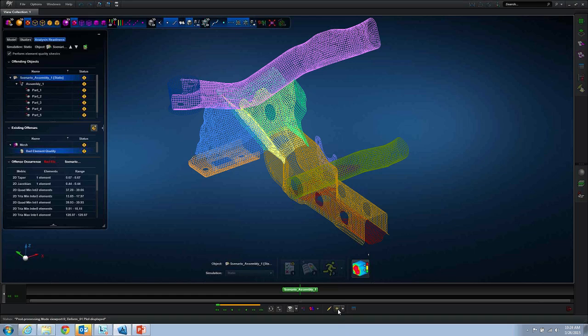Okay, and quickly we can look at what we call the hotspots identified. If I click on this one, it will show me where in the model there are the highest displacements, because it is set to displacement at this point in time. You can even ask how many you would like to display, whether 4 locations or 25 locations, whatever the case may be, and it will highlight all those in the model.